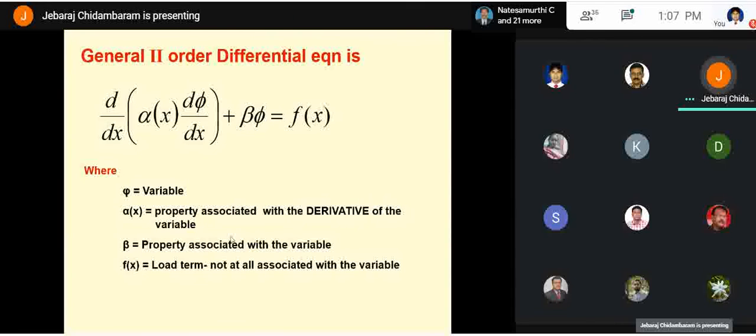In that, increase your number of elements, h-refinement. Increase the order of polynomial, p-refinement. Then you get an improved result. Converge, and you can be confident of your design. Give this confidence to your students so that they need not be panicky. They can do new things with that.